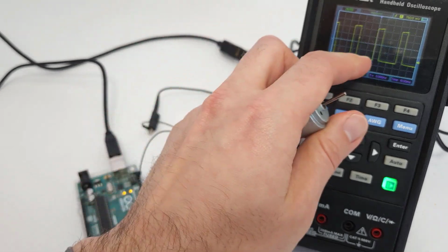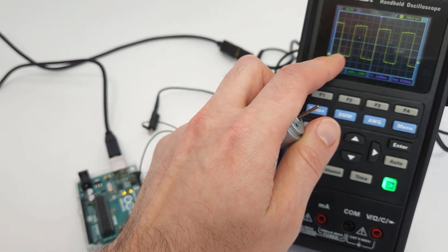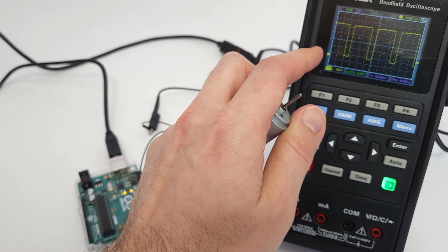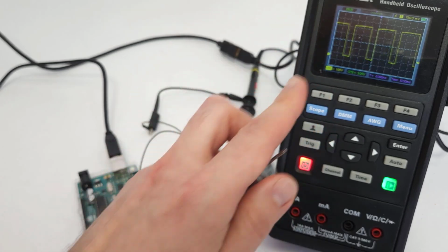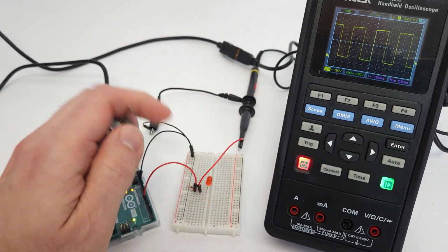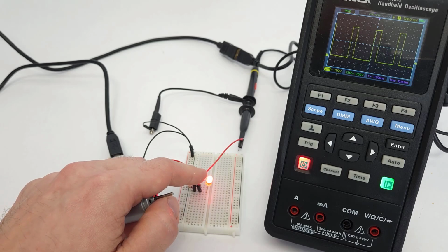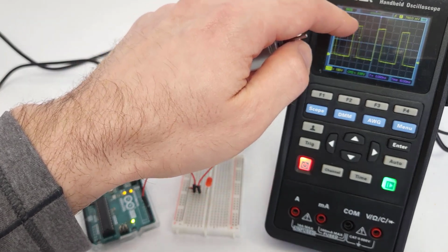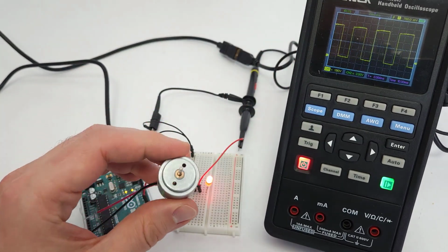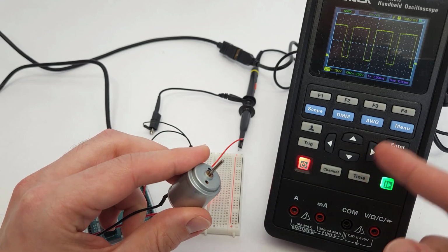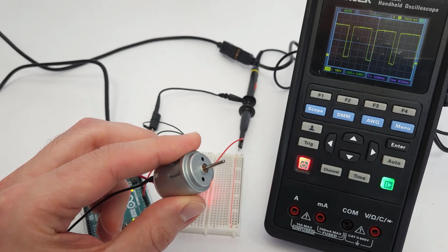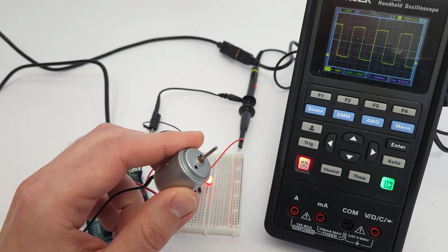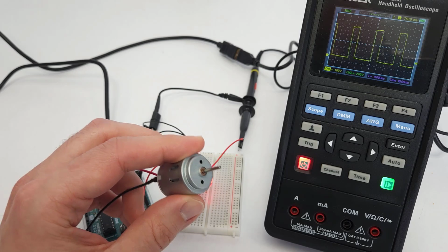It's not necessarily always going to be a clear-cut linear relationship where 0% duty cycle corresponds to off, 100% duty cycle corresponds to completely on, and you get a linear relationship in between. Even with the LED, you may have noticed back earlier in the video that it didn't necessarily look like a linear brightness fade as the duty cycle went between 0 and 100%. You might get the same thing with a motor, where it's not necessarily a linear relationship between speed and duty cycle, because you have things like internal friction in the motor that it might not be able to overcome at very low duty cycles, so it might not spin at all.